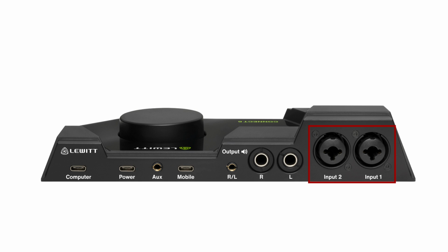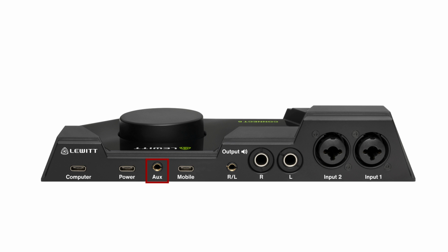If you want to bring in a line level signal from a phone, a mixer, or another source, there are a few ways you might be able to do it, depending on the audio interface that you're using. On the Connect 6, there are two combi inputs on the back that accept either XLR or quarter-inch, but those are already occupied by my two microphones. Fortunately, there's also a stereo 3.5mm or 1/8-inch input labeled aux. Using an aux cable or an adapter, I can connect basically any analog line level source with this connection.